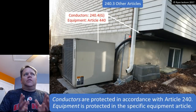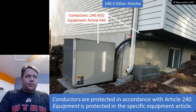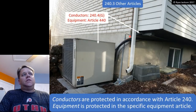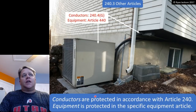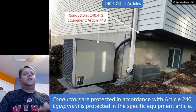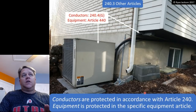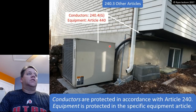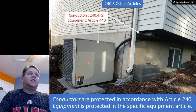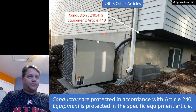Okay, let's get into the rules. 240.3: Article 240 is overcurrent protection, and 240.3 gives us a general statement. It says conductors are protected in accordance with Article 240, and equipment is protected in the specific equipment article. All right, so for the conductors supplying the air conditioner, I go to Article 240. For the equipment itself, I go to Article 440.